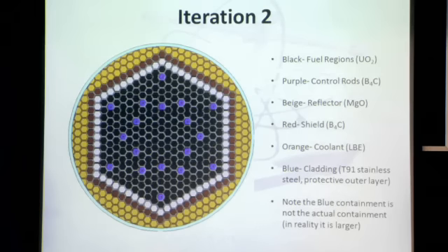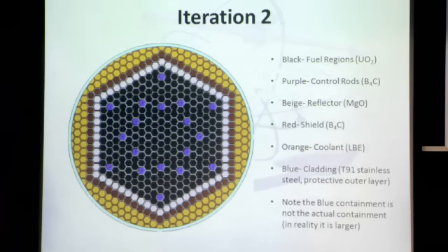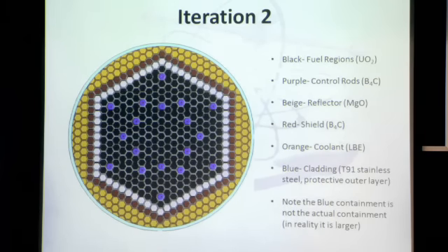Yeah, that makes sense. Well, then I have a question for the secondary side folks as well. Usually when you worry about a loss of load in a reactor, you only have one load, it's the grid. But in this case, you guys have two loads of the same magnitude, electricity as well as process heat. Have you guys looked at what to do in the event that just one of them goes down? Will you have to lower the power produced, or would you be able to send the rest of that either electricity or process heat to the other process and keep things going?